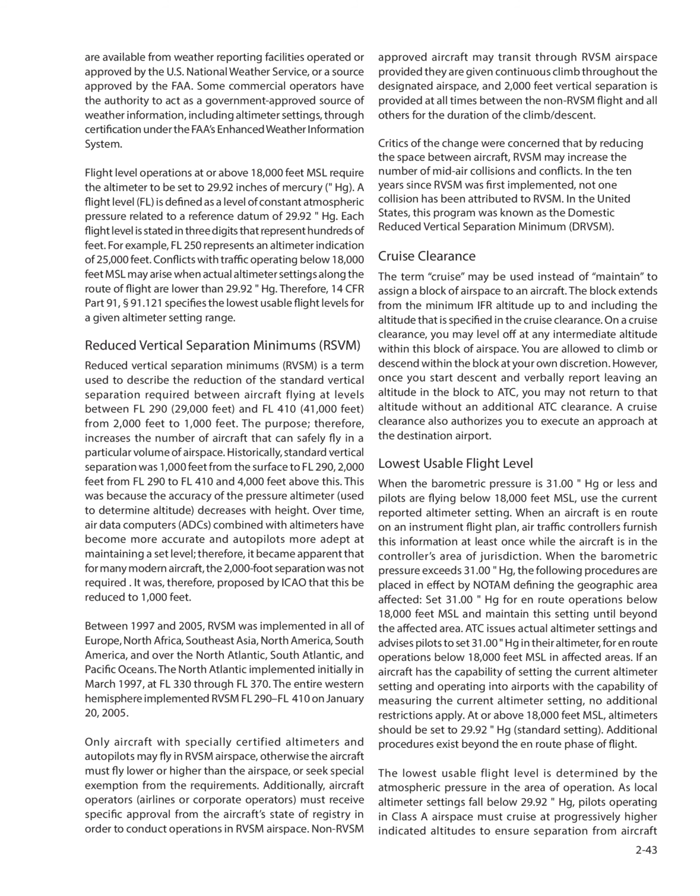The North Atlantic implemented initially in March 1997, at FL-330 through FL-370. The entire Western Hemisphere implemented RVSM at FL-290 to FL-410 on January 20, 2005. Only aircraft with specially certified altimeters and autopilots may fly in RVSM airspace, otherwise the aircraft must fly lower or higher than the airspace, or seek special exemption from the requirements.